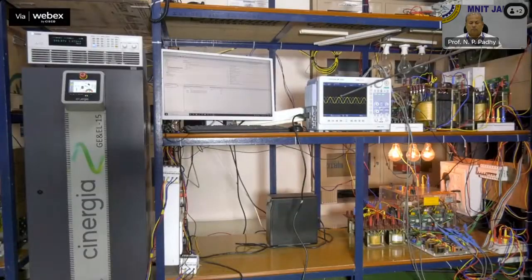The control loop is enabled, and the synchronization to the grid voltage is ensured by the PLL. The MPPT and DC link loop will track the maximum power giving the reference current, and the current control loop will further track the reference current. So, in this way the maximum power point is getting tracked.